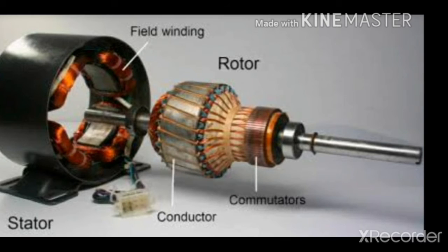And now let's see the next classification, the DC series motor. A DC series motor will have the winding in series form. That is, the series motor is connected with the armature and the field winding in series with a common DC power source. The motor speed varies as a non-linear function of load torque and armature current. And current is common to both the stator and rotor, yielding current squared behavior. Here you can see this part indicating the shunt winding.